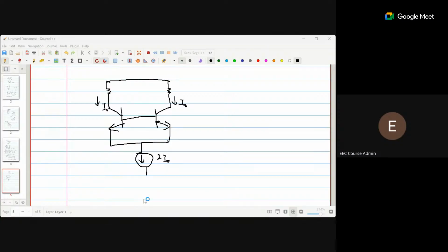When does that happen? In that case, is it the one where the current has steered to one side? If input 1 is large or input 2 is very low, then the transistor at input 2 will turn off, and the first one stays turned on, because we have to maintain the balance of 2 I naught. Yeah. It's not totally clear. Anybody else?